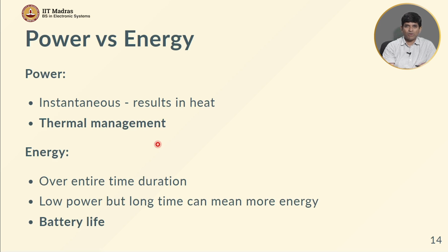That is good. The problem is, if I bring down the frequency, it also means that a given set of instructions that I have will take longer to execute, because it takes that much longer for that many clock cycles to execute. I still need 1 million clock cycles. It is just that each clock cycle is now, let us say, 1.2 nanoseconds instead of 1 nanosecond, right. So, it takes longer for me to execute. Now, from a power point of view, that is good, right, because my maximum power has reduced and therefore the heat that I produce is less. The issue is the energy remains the same, because even though my power came down, the time increased. Okay, so power into time remains the same.